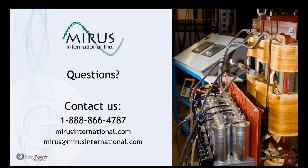So yes, it does introduce some losses. We have also found in many applications that the application of the filter improves the operation of the drive and whatever it's supplying, be it a pump or a fan or so on. So the end result is a net reduction in power consumption with the use of the filter, because it increases the DC bus voltage and actually improves the operation of the drive. A quick question that I see: please list the IEEE standard number dealing with the filters. That's IEEE 519. That deals with harmonics and all the issues associated with it.